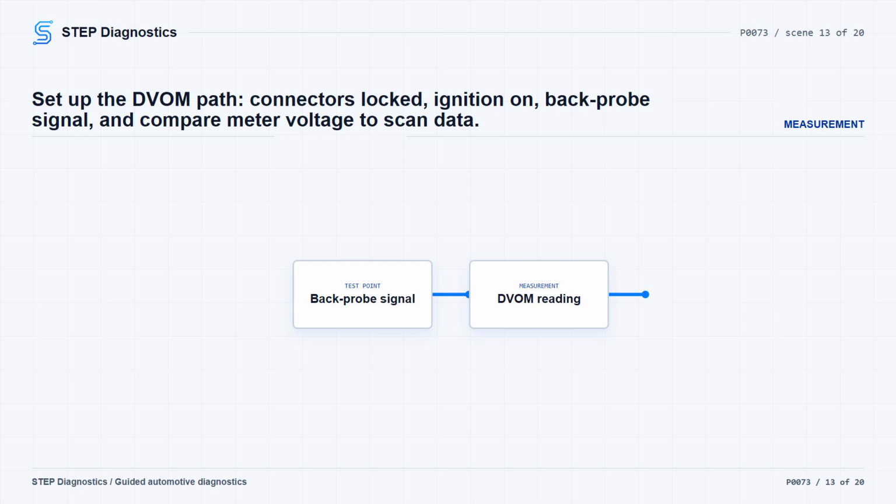If the circuit fault is active and the scan tool voltage does not match the DVOM voltage, the ECU is suspect. A constant voltage above 6.0 volts points to the signal circuit shorted to another voltage supply. A constant 5.0 volts points to an open farther downstream, most likely at the sensor or the sensor ground side.